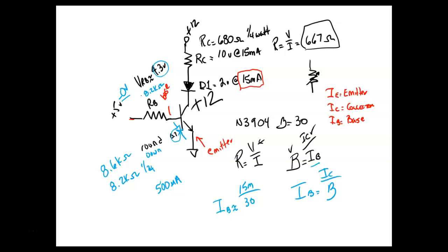Now, fuses won't measure 0 because fuses deal with I squared R. This is what melts the fuse, so it's got to have an R component. So fuses will drop a voltage, but it's going to be very little. The lower the current rating, the more they'll drop. So you've got a 10 milliamp fuse, it might be 10 ohms. But 10 milliamps times 10 ohms is still nothing in volts, right? You understand that? So the lower the rating of the fuse, the more resistance it's going to have. The higher the rating of the fuse, the less resistance. So these big old fuses, they'll measure 0 on our meter.